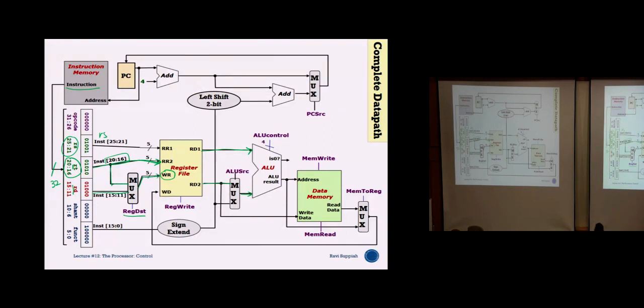Similarly, over on the ALU side, there is some data that is going to come here, and the lower 16 bits will get sign extended and also come here. Then you have a multiplexer there to decide which data will be channeled to my ALU to do the operation. And finally, when I get the ALU result, what does this result signify? Is it actually the answer that I'm looking for? Is it an add instruction, or was it a load word type of instruction where the ALU operation is actually giving me the address? We do not know.